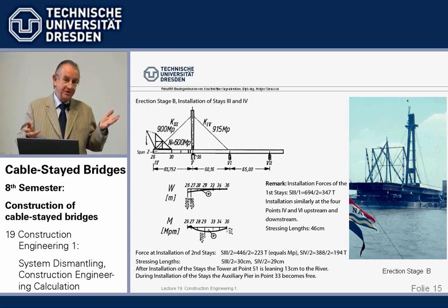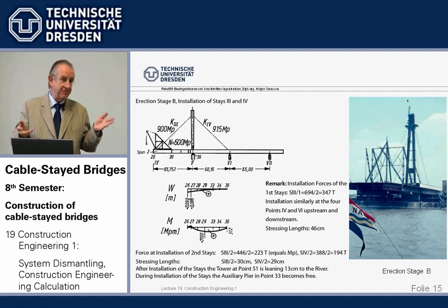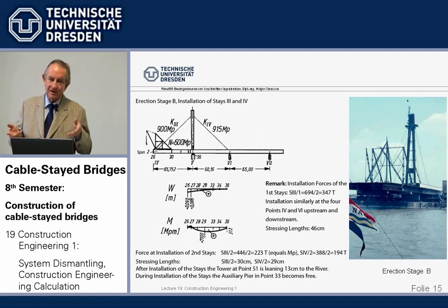I just warn you. And of course, naturally, the derrick is always much heavier than you have assumed in your calculation. I've never had it that a derrick had the weight of what was assumed. A rule of thumb is lifting equipment will weigh 1/2 of the weight to be lifted.